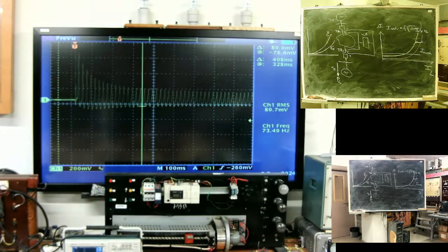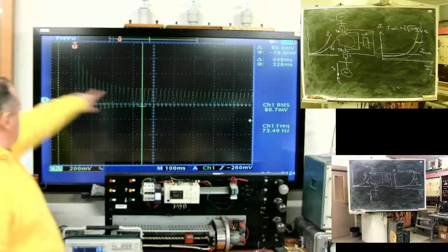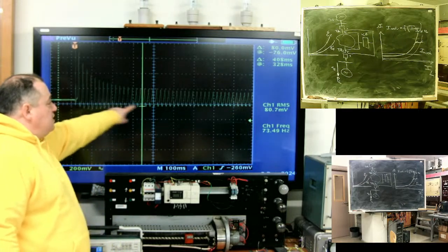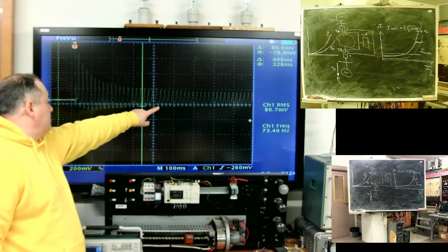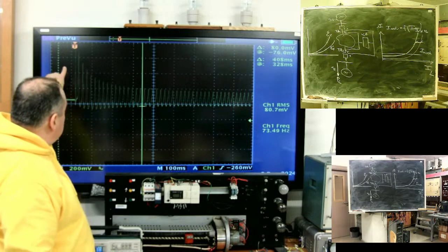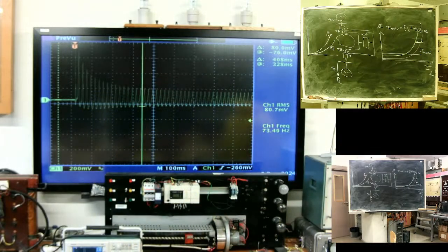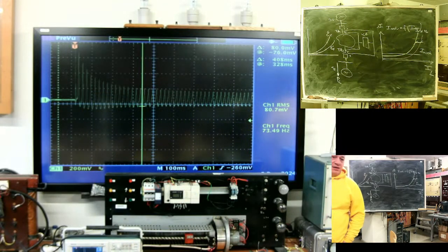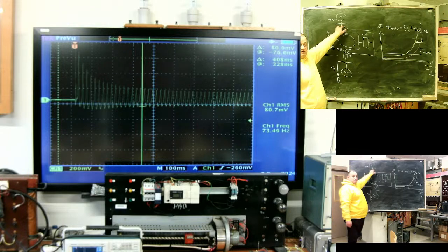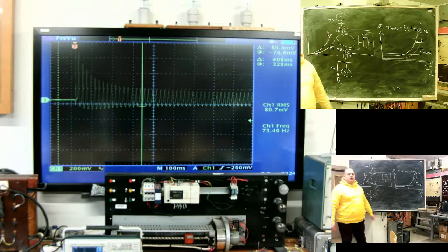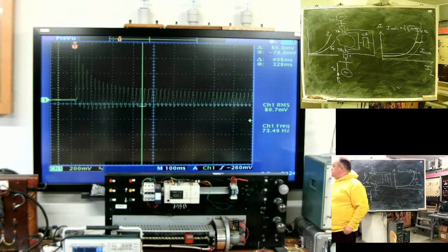Single try for the A phase. Nice, isn't it? And it's not a sine. It will become a sine later. But at the starting point, you see, it's not a sine, and it has a huge exponential component. Inrush current, at the moment the first switch operates, we will see this flowing through our protection.